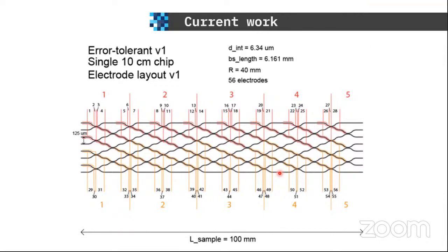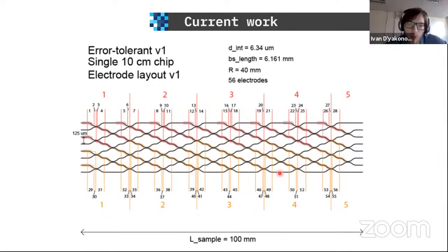So do you consider any approaches to cut the crosstalk in such dense circuits? So there are approaches to cut the crosstalk. You can, for example, fabricate isolating trenches between the waveguides, which will prevent the heat from going from the heated region towards other arms of the interferometer.